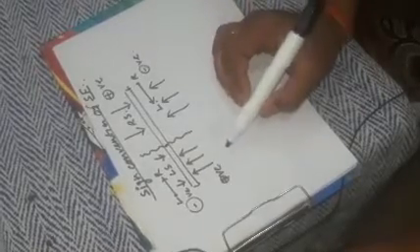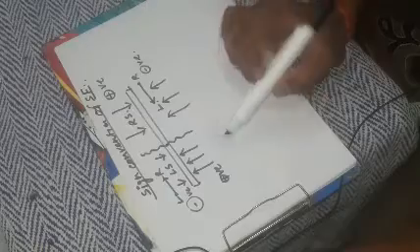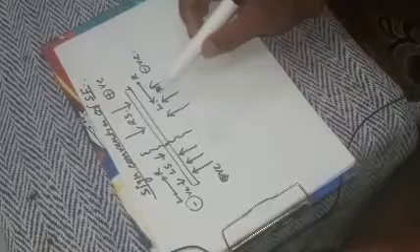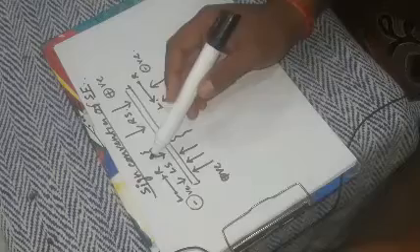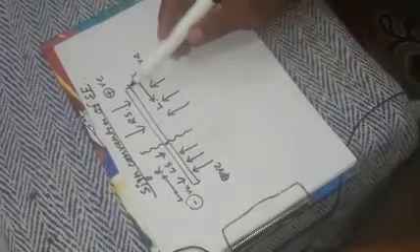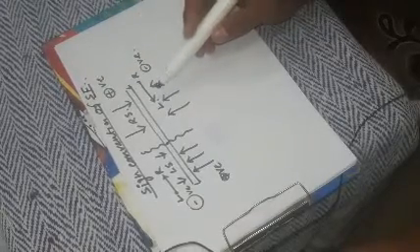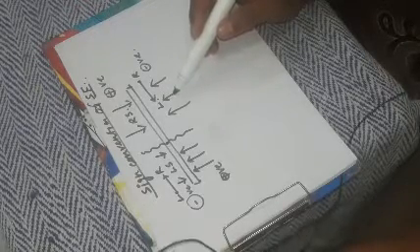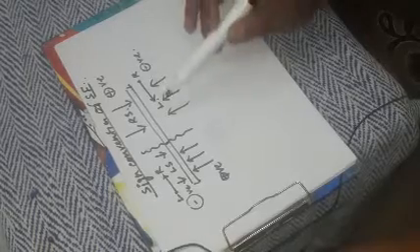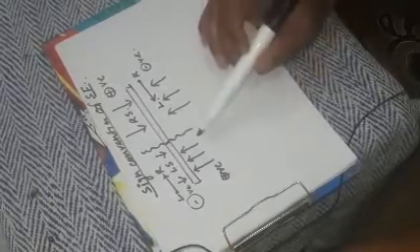Do remember, this is not a mandatory case. Each book differs with the concept. In some books, this is reversed. For the left segment, they consider downward forces positive and upward forces negative, and for the right segment, downward forces negative and upward forces positive. In your book bank, Strength of Material by R.K. Rajput is given. In that book also, the reverse is considered.